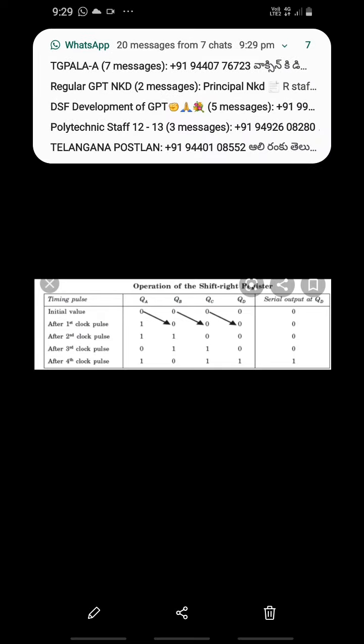And next, the second method. Let the D input be equal to 1 and Q equal to 0 0 0 0. All data inputs except the one on the left are zeros. The first positive clock edge sets the left flip-flop and the stored word becomes Q equal to 1 0 0 0.